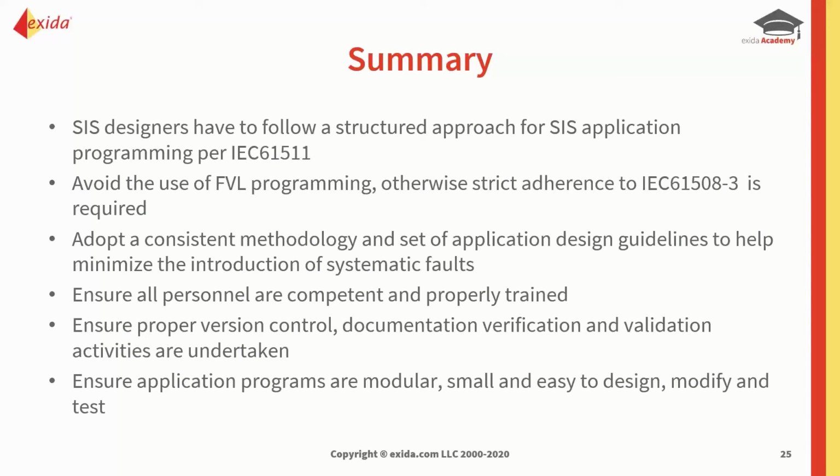Make sure that proper version control and documentation, verification and validation activities are undertaken. So we should be, for each of the modules that's written, or if it's on a SIF basis, we test them individually. We make sure that we can verify full compliance with the SRS for the SIF. And then finally, we do an overall validation to bring everything together. And that's usually what happens during the FAT, the factory acceptance test, which now is, instead of it being a highly recommended step, a mandatory step. We need to do an FAT.